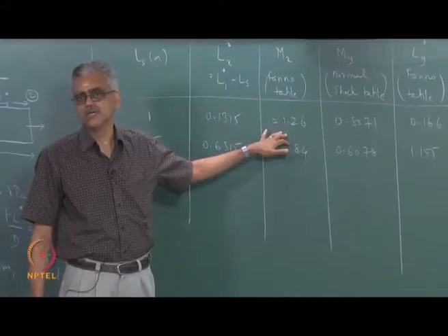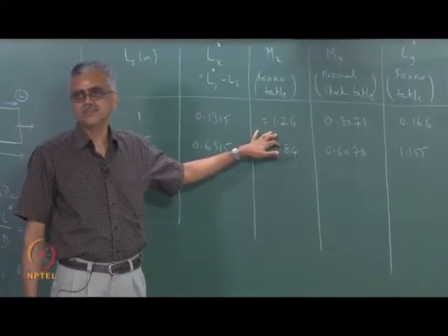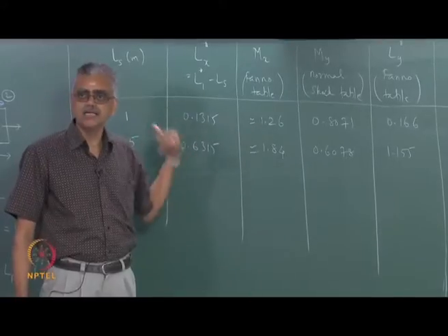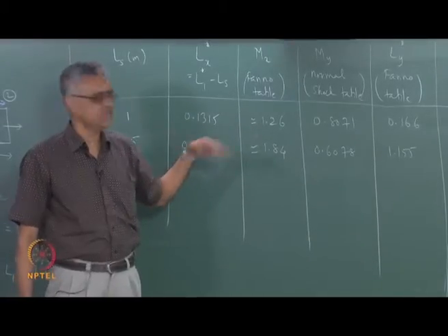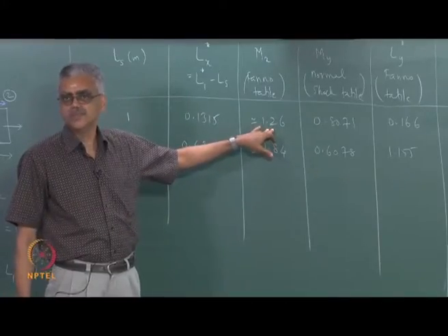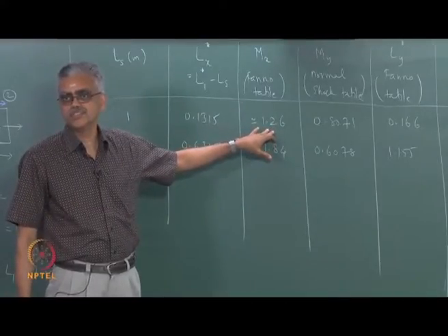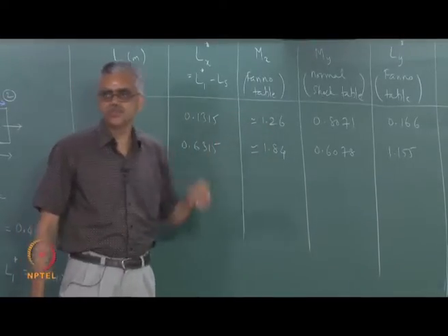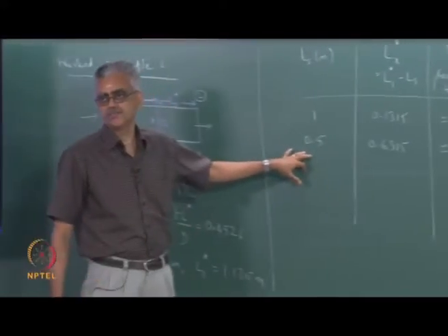Remember, from normal shock, the higher the initial Mach number, the lower the after-shock Mach number. So that means this must occur earlier in the duct. Again, you can see that this M is also very close to 1 actually, so that means this is not going to be strong. So we want it to be moved upstream, which is why we made a guess of 0.5.